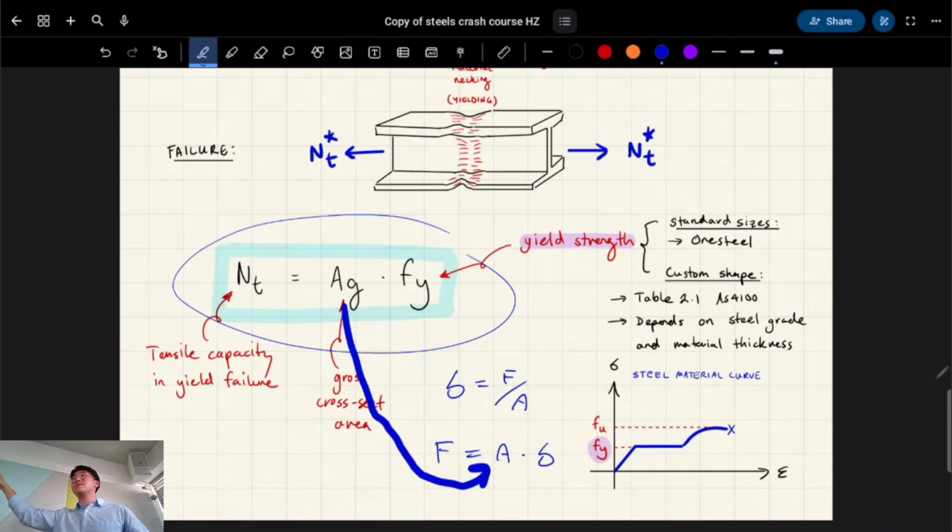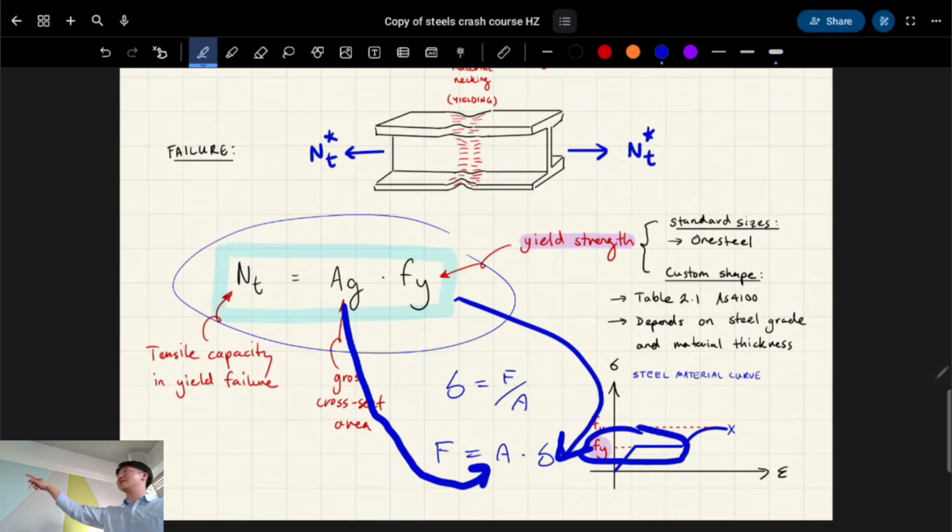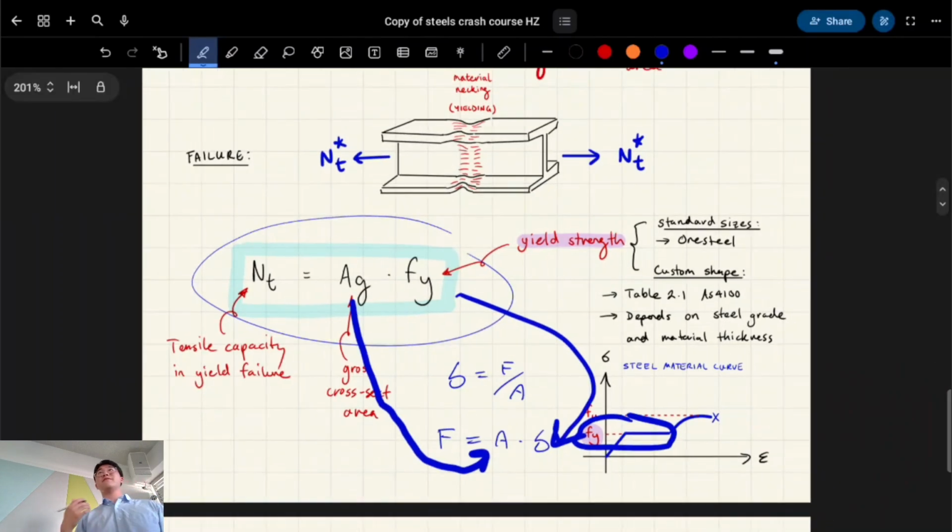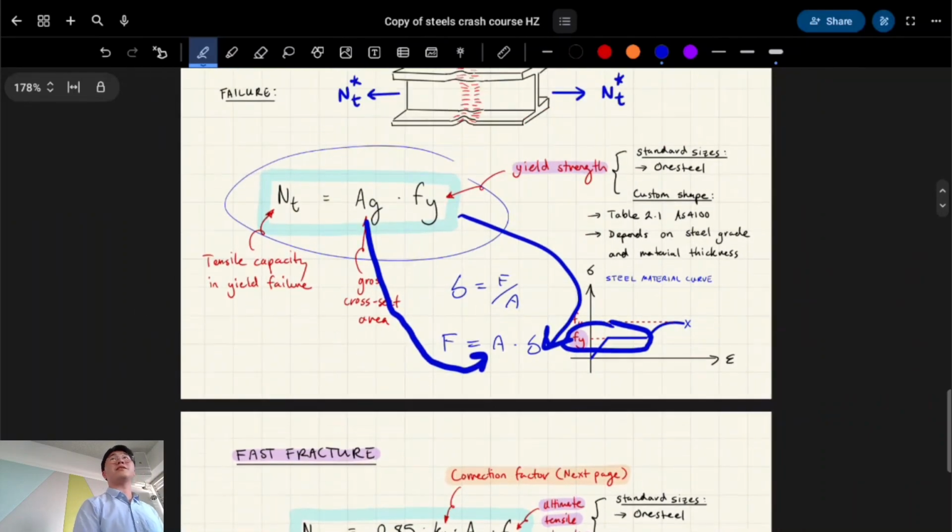The force that we're calculating is going to be the product of your gross area, which is the area without holes, so the cross-sectional area, multiplied by yield strength. Yield strength is the limit of the stress which our section can take, so we use F_y instead of sigma as in the general stress expression. That's what we're going to be plugging in. Is anyone still copying that down?